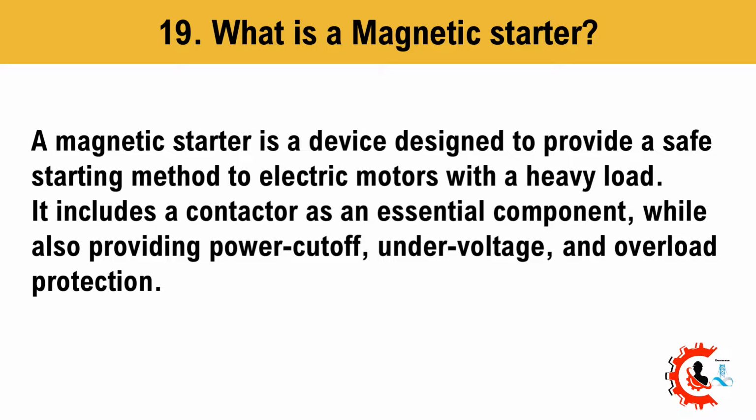19. What is a magnetic starter? A magnetic starter is a device designed to provide a safe starting method to electric motors with a heavy load. It includes a contactor as an essential component, while also providing power cutoff, undervoltage, and overload protection.